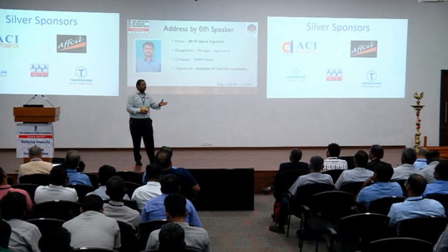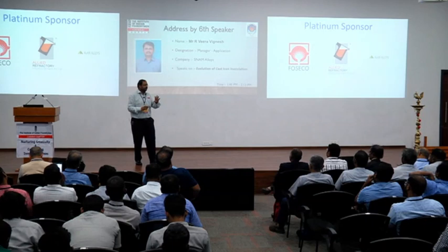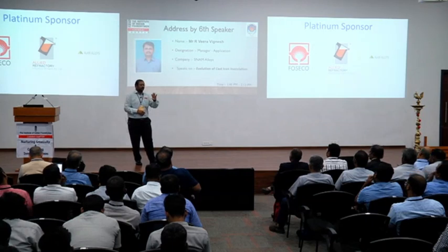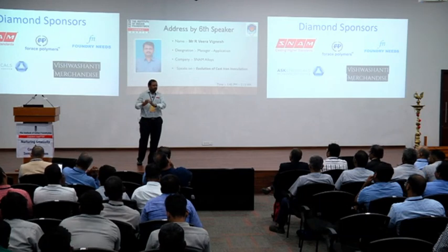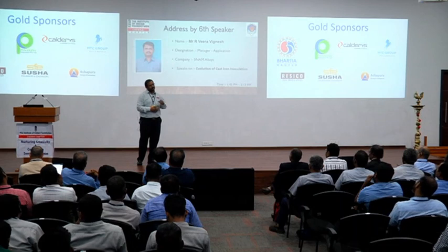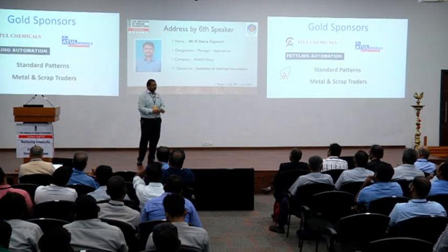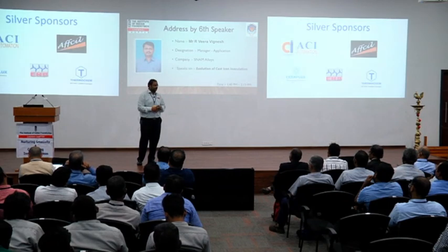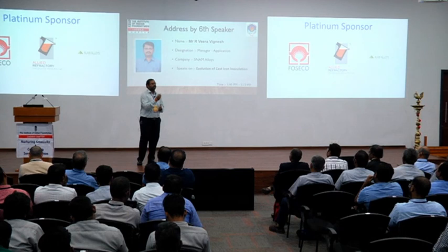So barium is a bigger atom, aluminum is not a bigger atom, but aluminum's reactive tendency for a given temperature is more. So for example, some foundry conditions with respect to liquid metal, I am not talking of the casting or the severity of the casting or the size and section thickness of the casting. So the health of liquid metal determines what inoculating element can be selected and to what level it can be added. So it is basically your potency of liquid metal.